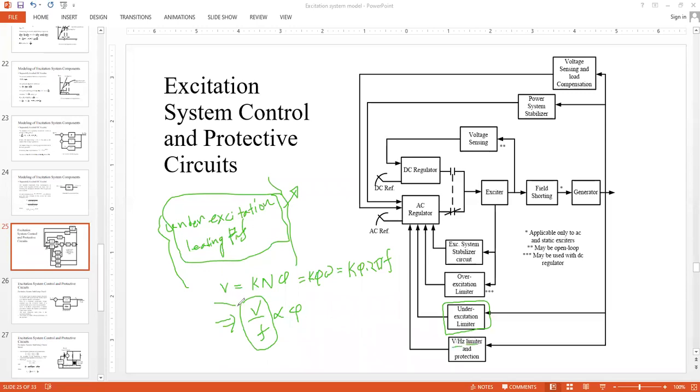If you don't limit this ratio to a certain value, then your phi will be affected, isn't it? And we all know if phi is affected, then either overexcitation will happen or underexcitation will happen, right? So this ratio actually indirectly affects the excitation of your system. It actually affects the phi.